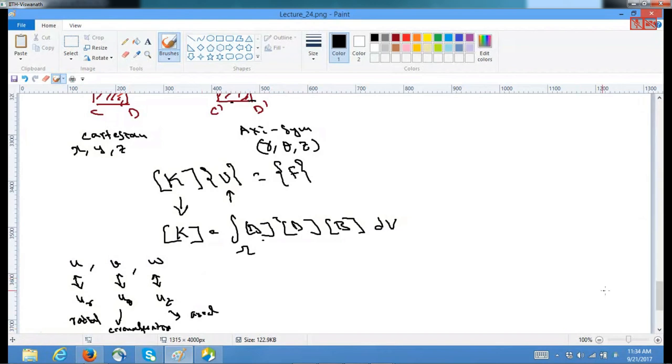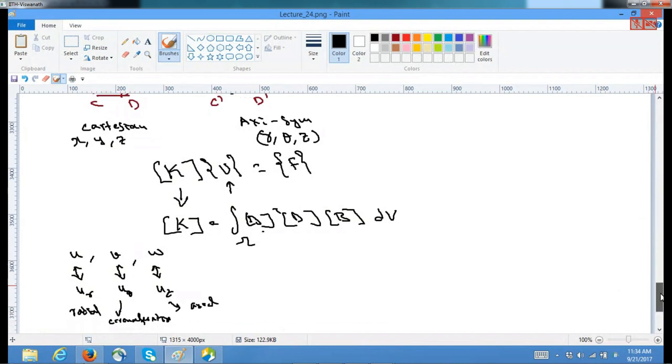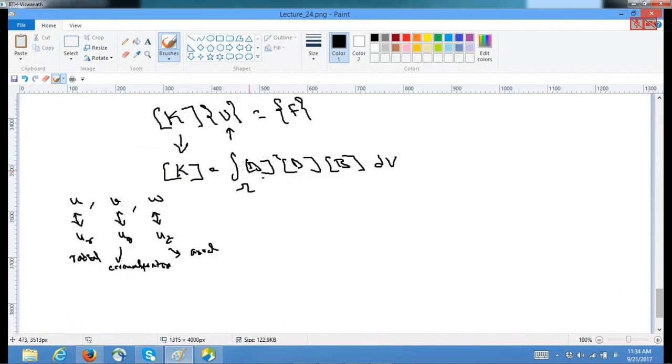So for this, since it is axisymmetry, the displacement v has to be 0. It has to be independent of theta, meaning u theta has to be 0, and because of that we can directly write tau r theta equals 0 and tau theta z equals 0, and hence also gamma r theta equals 0, gamma theta z has to be equal to 0.